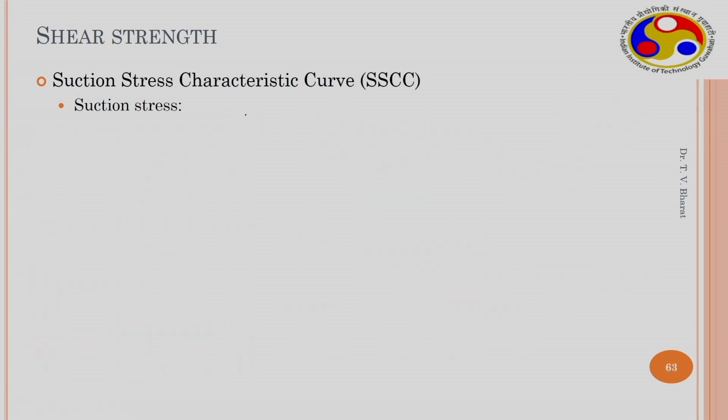So, we have the sigma s data, therefore, now the effective stress sigma dash is equal to sigma T minus UA, this is the net normal stress, plus sigma S dash plus sigma C naught. So, this is the initial cohesion, this together is sigma S, that is what we got now.